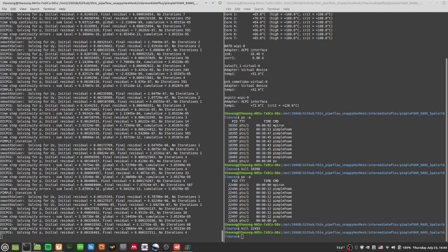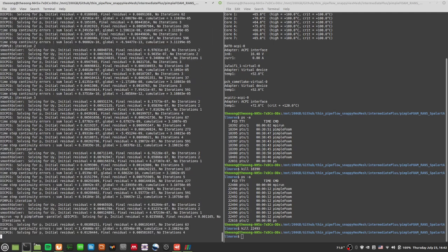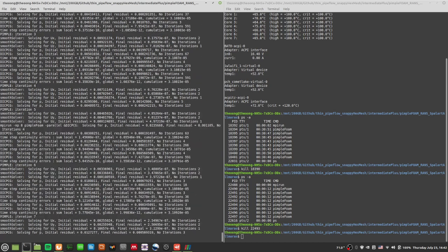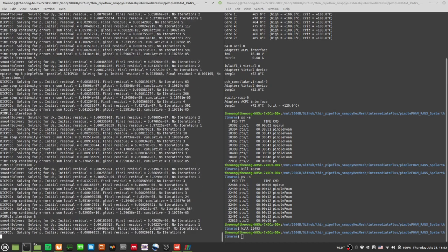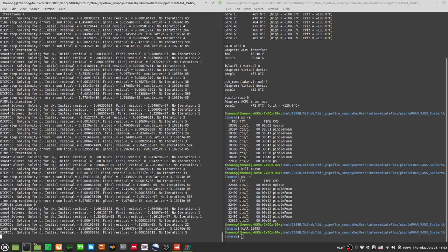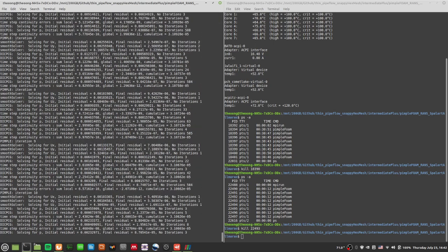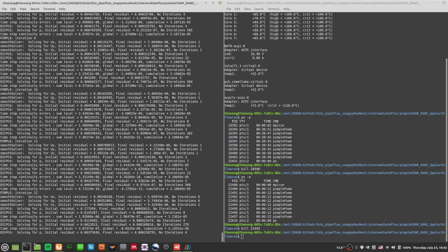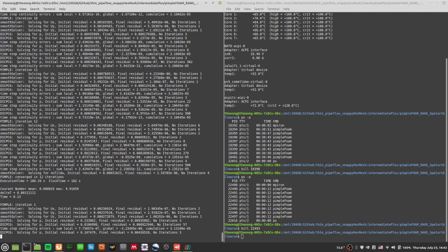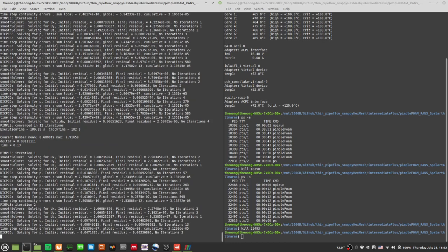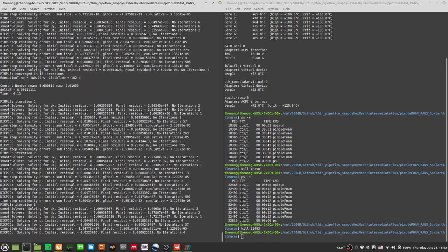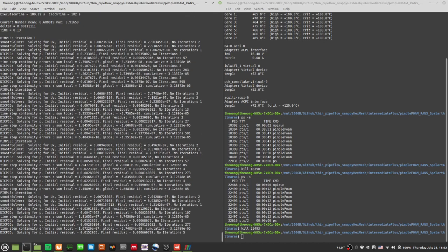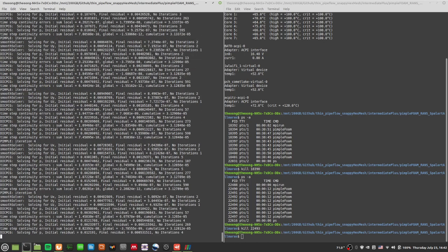So now the thing's running well, and OpenFOAM seems to be giving us the intended results. So it shows that if you tweak around the relaxation factors and maximum Courant numbers, you will be able to get some semblance of stability.